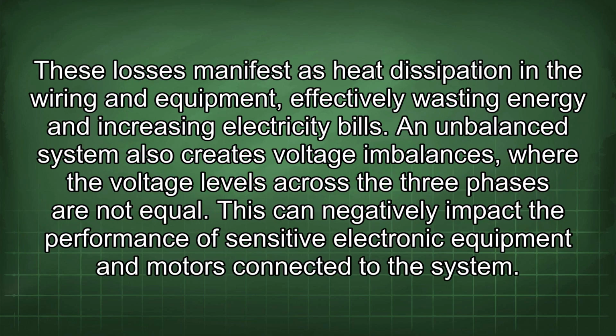These losses manifest as heat dissipation in the wiring and equipment, effectively wasting energy and increasing electricity bills. An unbalanced system also creates voltage imbalances, where the voltage levels across the three phases are not equal. This can negatively impact the performance of sensitive electronic equipment and motors connected to the system.